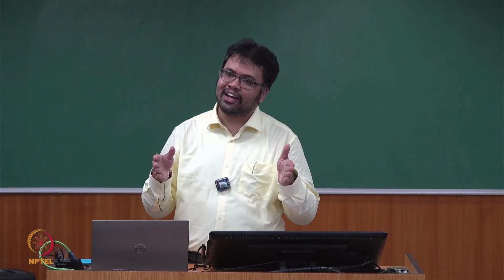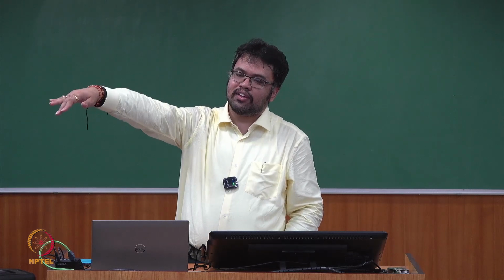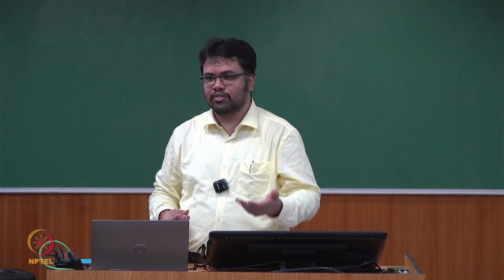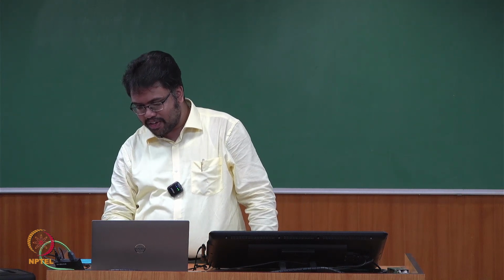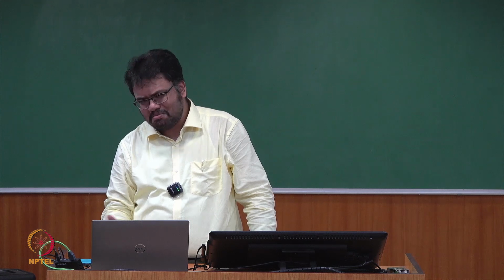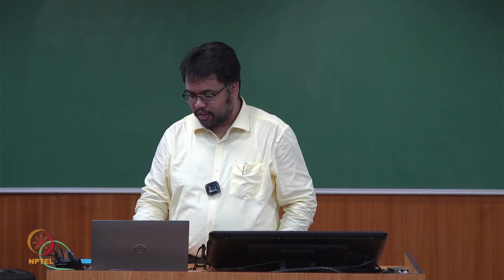So we cannot directly say this part is transient and this part is steady. More or less, once e to the power of minus zeta omega t becomes more or less 0, we can say it has now become steady. It's not exactly 0, but practically 0. So we need to find that practically zero point. I could say it becomes steady around this point, which is agreeable, but obviously I should not say it becomes steady at this other point. That's not correct, so you have to apply judgment about what is happening there.